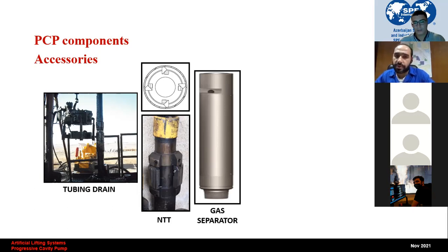The concept the gas separators work on relies on forcing the fluids to move in a circular path, and using the concept of centrifugal force to repel the free gas outside. Then the free gas can exit from that hole outside to the casing and not enter into the pump intake.